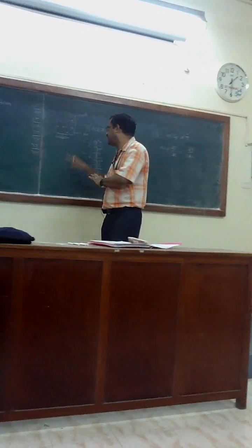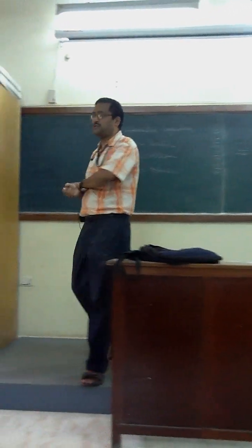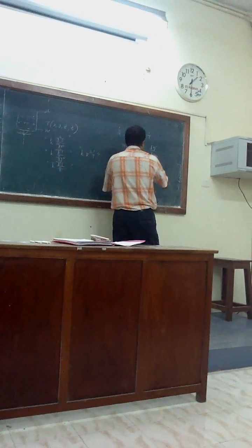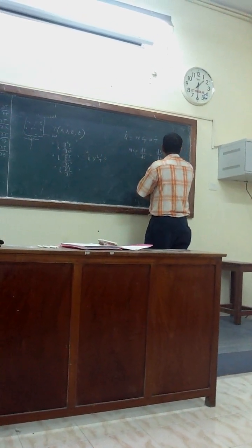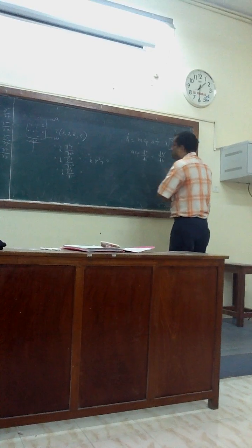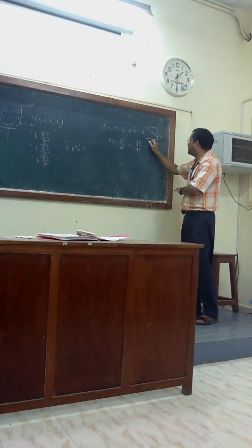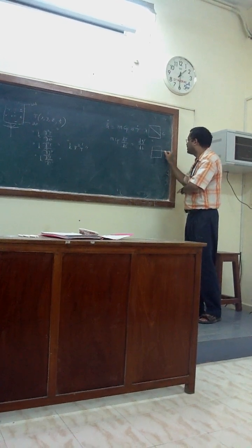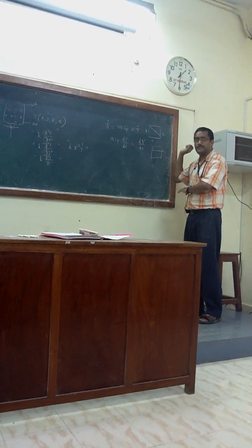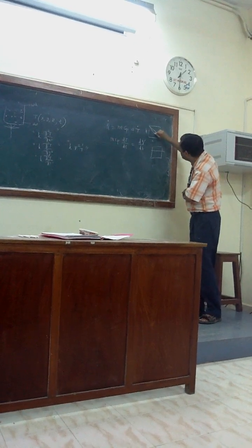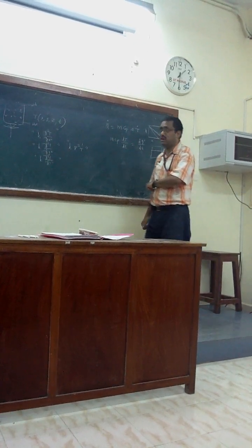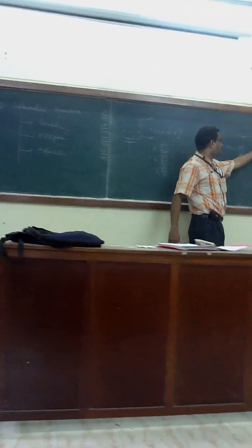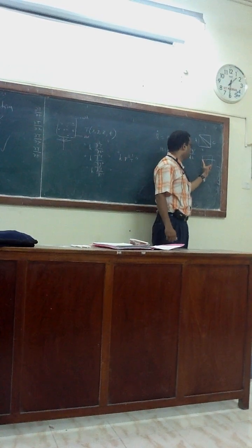If the system resistance is there, point to point the temperature will change. For example, you have a wooden block, hot wall, cold wall, and this is the temperature profile. So in this type of thing, along the x there is a resistance. If there is no resistance, the temperature is like that. If there is a very high resistance, it will be very steep. So based on thermal conductivity, people can conclude: if thermal conductivity is tending to 0, you will get this kind of profile. If thermal conductivity is tending to infinity, this kind of profile.